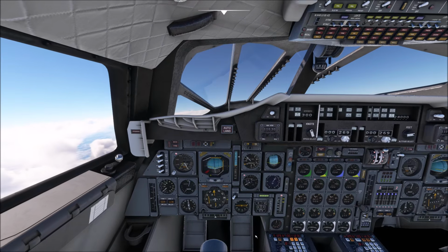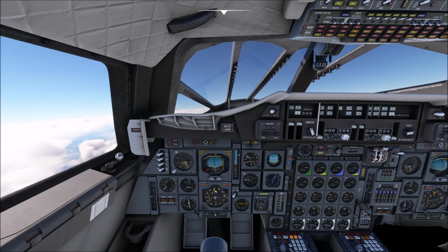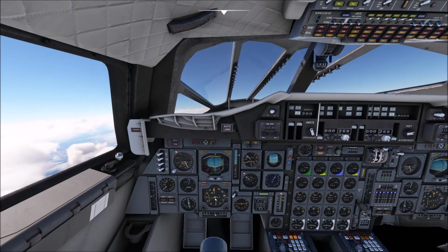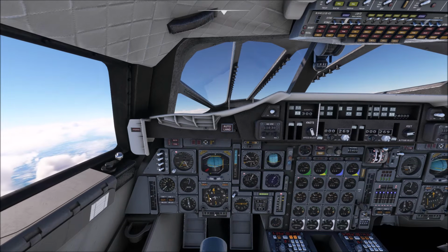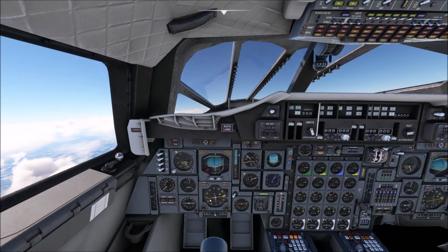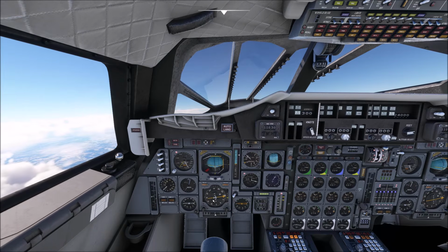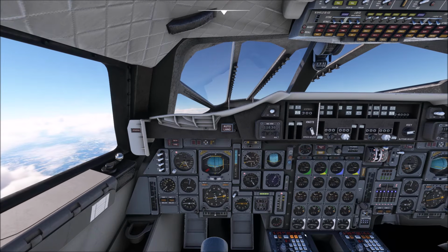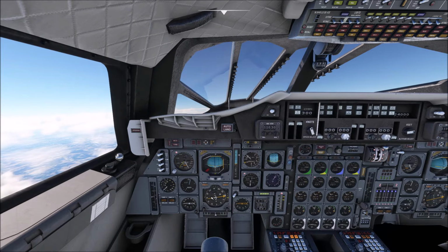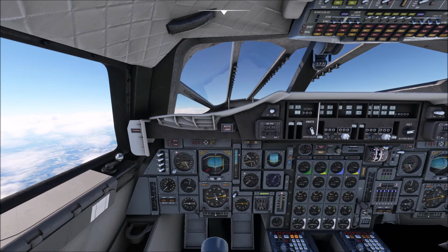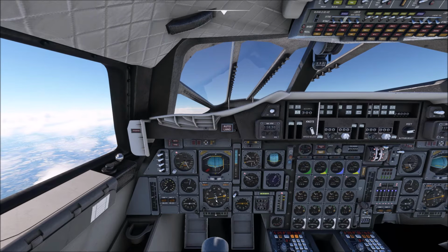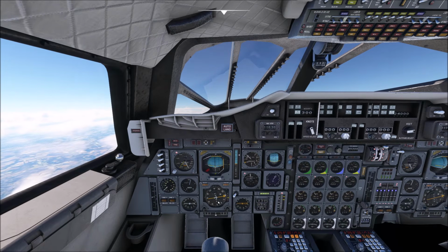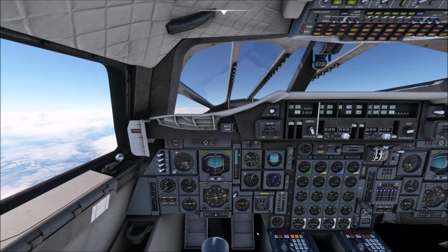So all tracking well here. You notice the HSI is often tracking off beam. It's because this is picking up every waypoint between EGLL Heathrow and JFK, London to JFK New York. What the INS does is skip all those in this coding to just track onto the next actual intersection, keeping it under 9, as I mentioned earlier at the flight planning stage, so that you don't have to keep re-inputting lat long coordinates.